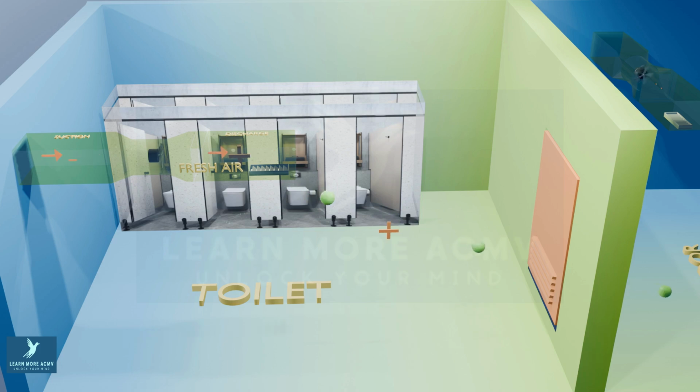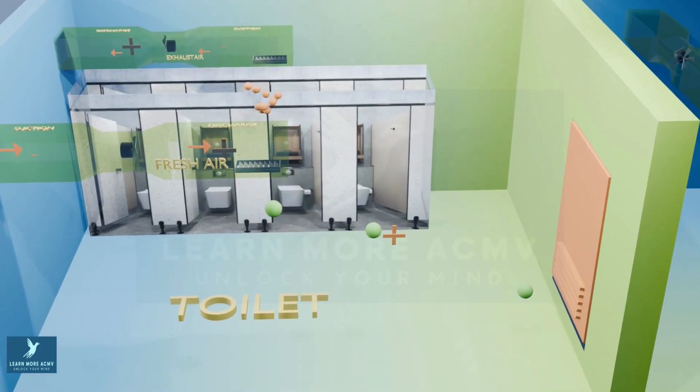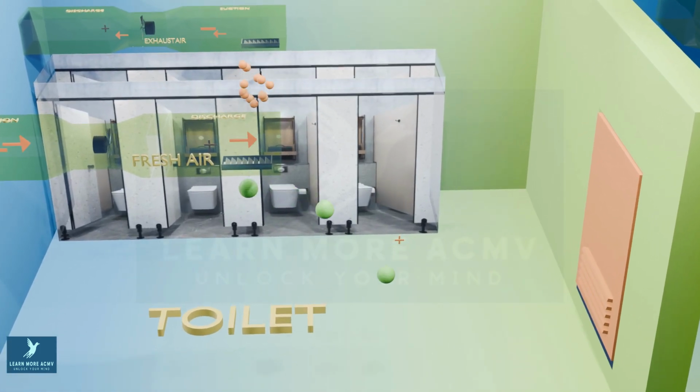When designing toilet ventilation with both fresh air and exhaust fans, the exhaust airflow must always be higher than the fresh air supply. This ensures the toilet stays under negative pressure and prevents air and odors from escaping to other spaces. But if the exhaust fan fails or stops running, the fresh air fan will push air out into other areas, which we don't want.